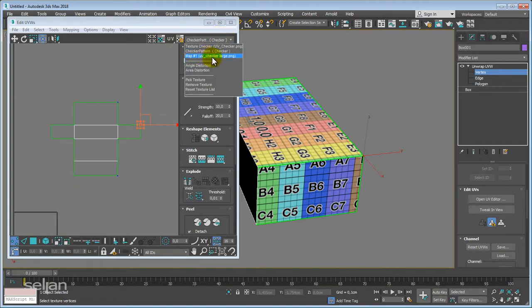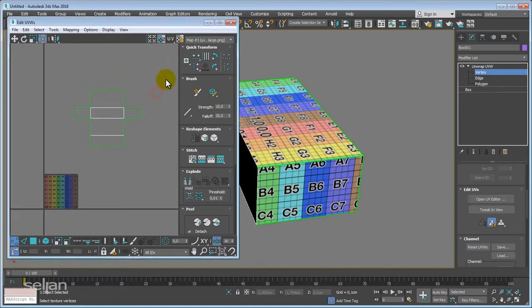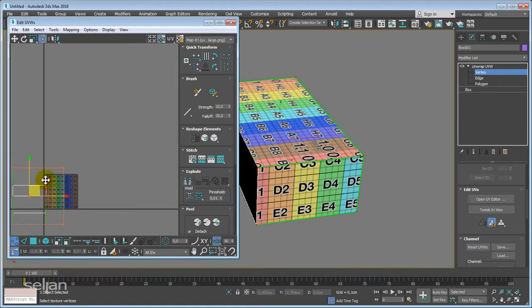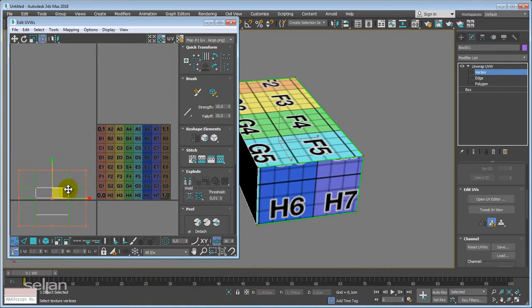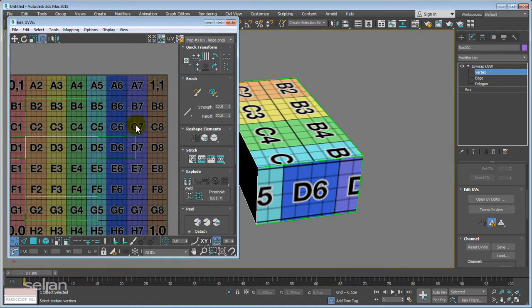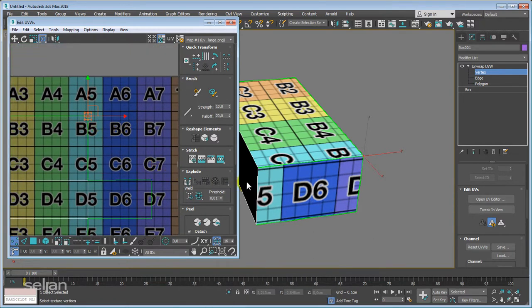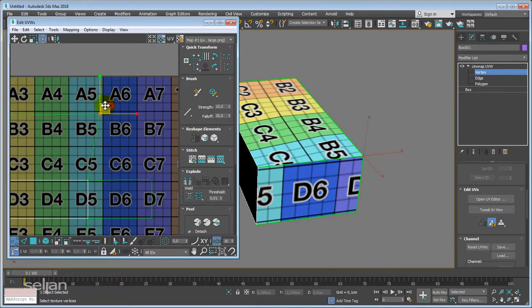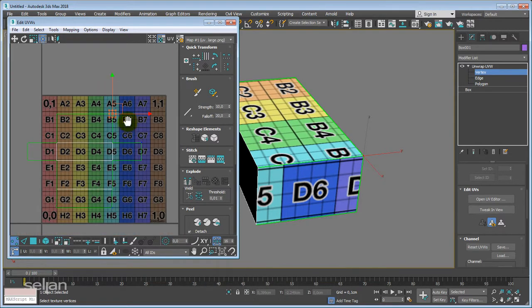If you want to give a better feedback, you can just open up the texture. So I'm using the UV checker large PNG and make it visible here. And now I can drag this whole system and move it and make it a little bit smaller. Move it here. And if I'm selecting this particular point, now you can read that's the D7. Now it's dividing the 7. So this is what happens. This particular point is actually matching with this one, and when I move it away, this is what happens. So the texture follows my changes in the UV.